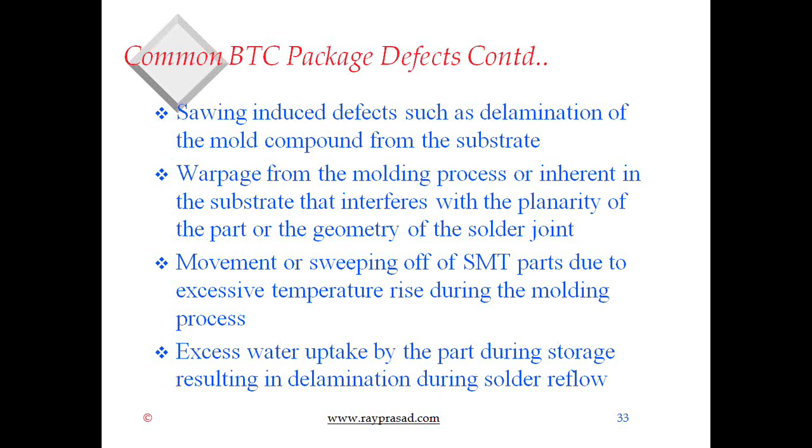And QFP, even if they are small, generally they are not moisture sensitive, but you have to check the data sheet because they can take a lot of water and cause the delamination during the reflow. So you have to treat them just like any other moisture sensitive package.